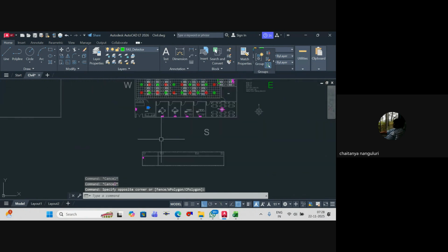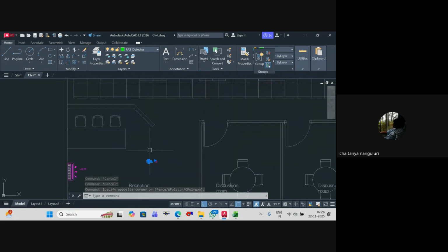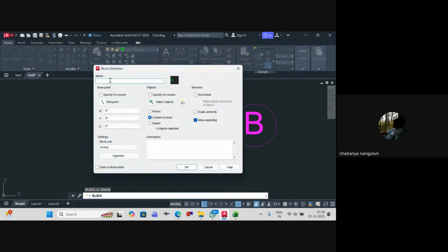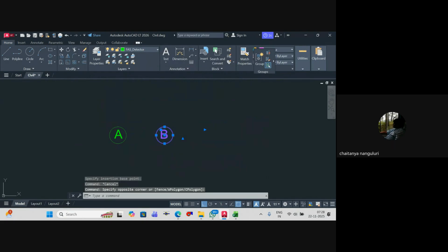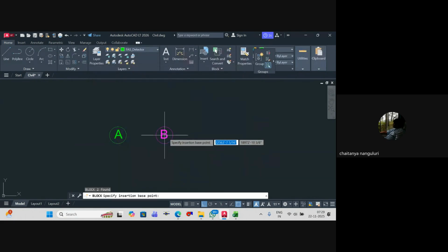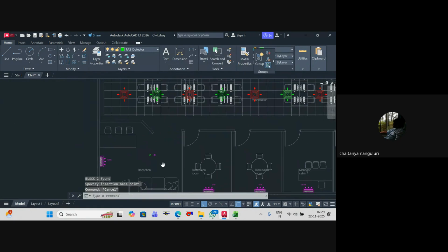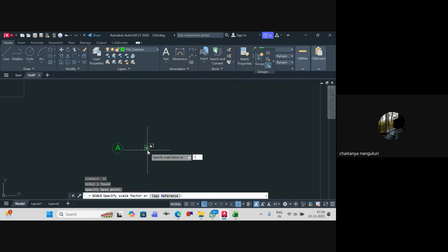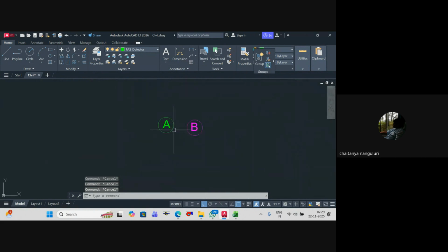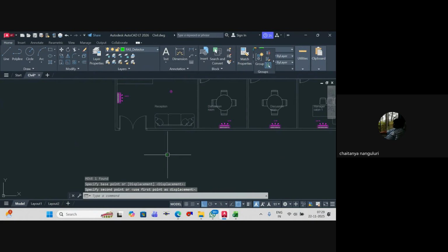So here I've got some beams as well, but that's okay. We'll avoid it as of now. So above false ceiling detectors, then we go to B, which is below false ceiling detectors. Okay, now I have to place these detectors, so I'll increase the size of this 1.5 times. So first we'll work on below false ceiling detectors.